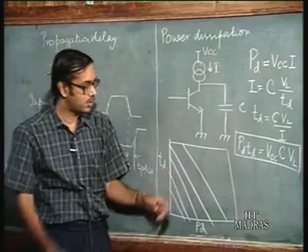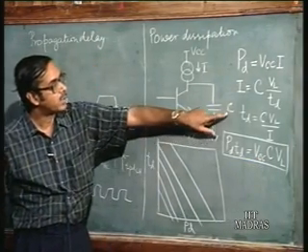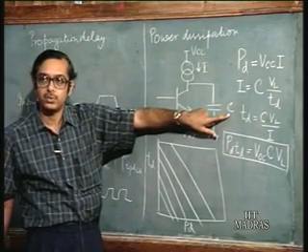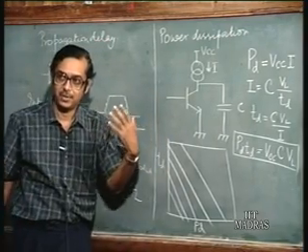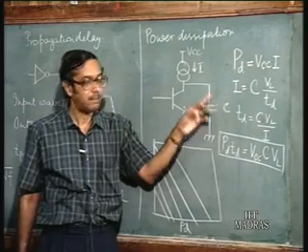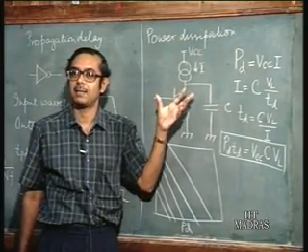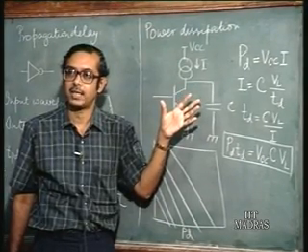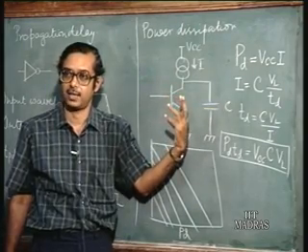But of course, you must also remember that this takes into account only a capacitance which is a constant. In view of the last class, you must remember that this is true only when the capacitances are the junction capacitance type for a BJT. If you have the diffusion capacitance, this capacitance is no longer going to be a constant, but again it becomes a function of current.